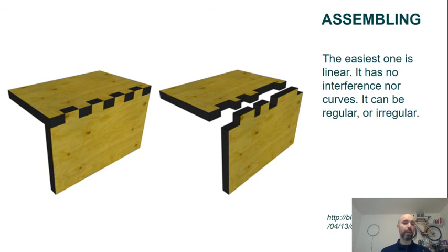The most common way to join two pieces that you laser cut is this. First of all, you never ever cut something straight. When you want to join them together, you have to make these snaps. The reason is actually simple. If you think about two pieces of wood that you cut and you try to create a connection between these two pieces of wood, you will never be able to get something very precise. It's tough to show you, but think about something that could slide back and forth or turn a bit. It's really not easy to align.